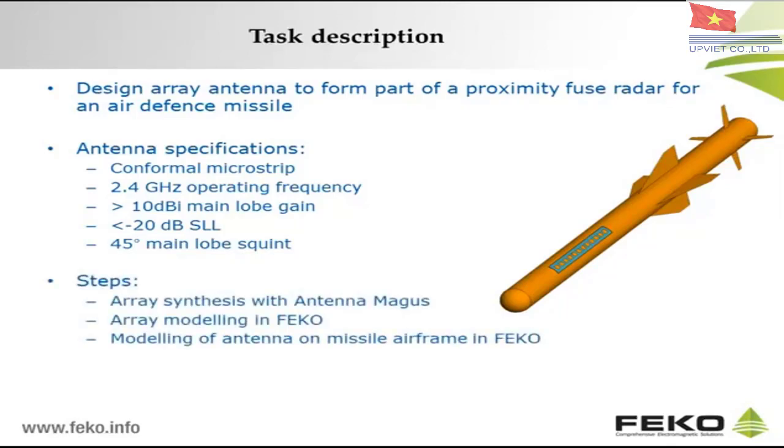We will start by performing the array synthesis in Antenna Magus before modeling the antenna in FEKO. Once the antenna is confirmed, we will mount it on the missile and simulate again to test if it works properly in the intended environment.